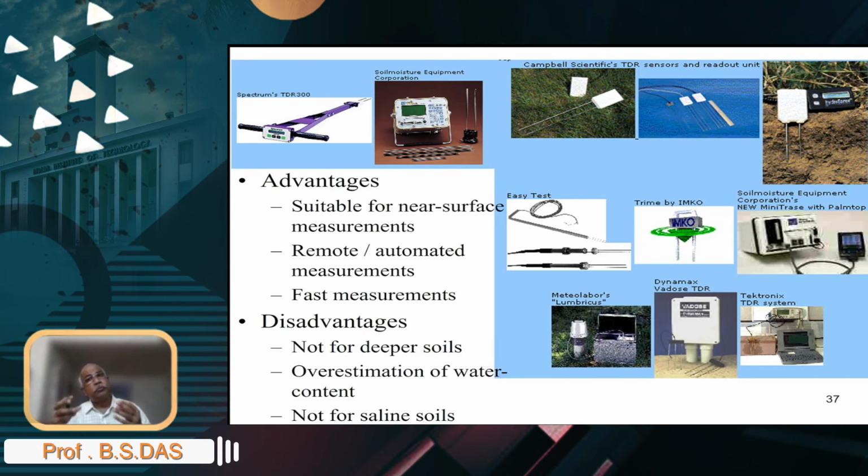So you should be able to measure every 3 centimeters from the soil surface, so you could almost do a near surface soil wetness measurement using this time domain reflectometry technology. The measurements are very fast. The whole process takes on the order of about 50 milliseconds.